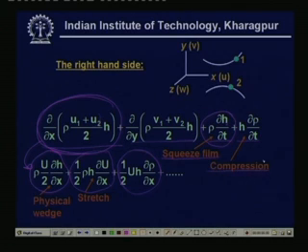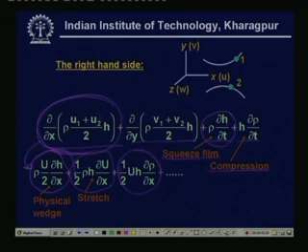That is simply termed compression. Now, in the present case of the Reynolds equation, you do not find all these terms on the right hand side. As a matter of fact, just have a look. We will only be considering this particular term, which is called the physical wedge.